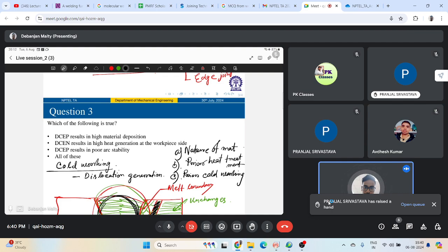Okay. Now, in terms of gas welding, as you know, this is also called oxyacetylene flame welding, and basically you're joining metals by heating with a flame that will be a result of reaction between fuel gas and oxygen, right? Oxygen and acetylene. Those are most commonly used gases which will result in a flame which will produce high flame temperature that will result in melting of your metal, right?